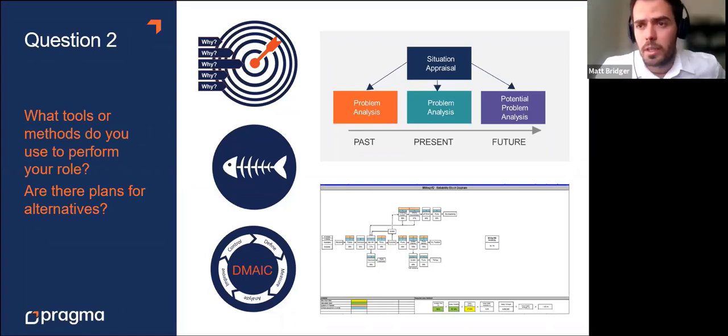Yeah, so as I mentioned earlier, my role's slightly different at the moment. So we're very busy with tactic development or review, and that's based on failure history, OEM manuals, and FMEAs. I've also been involved in developing and reviewing of maintenance KPIs over inspections, MTTRs, and top 10 breakdowns. And one side of it that's been quite important from a reliability perspective is we performed a criticality analysis on the one section, because that's our starting point for creating our optimum maintenance mix for the critical A's or those assets where we've seen concerns or issues.